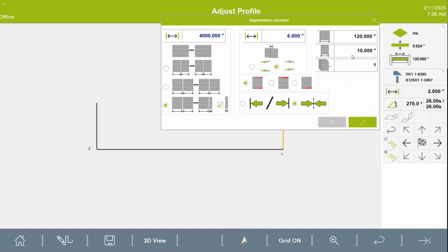So you got roughly 15 to 17 millimeters of disparity over your 10-foot machine, which is about 5/8 of an inch-ish. Okay, somewhere along that range. So a 10-inch part is not going to work with that much disparity. In this case, you wouldn't be able to use that.